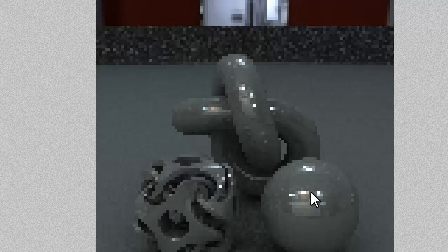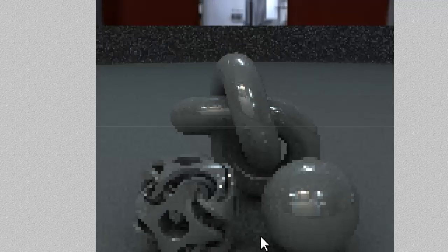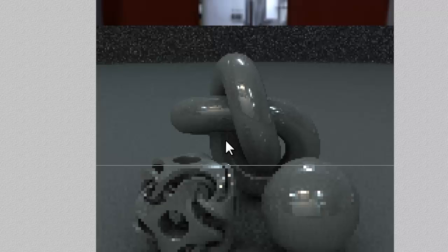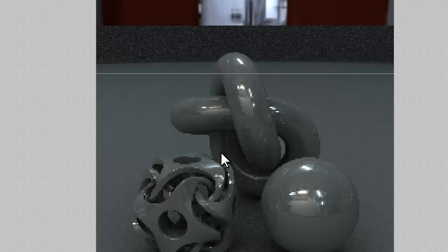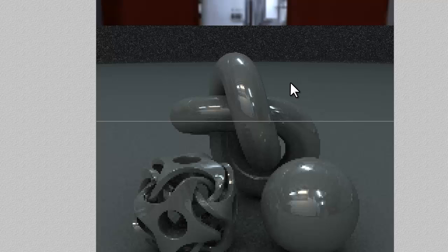Okay. So now if I render with this, I did it small so you can see the difference. We have got even lighting because it's a diffuse, and the simulated light sources generated at the world center spread out quite evenly on the diffuse inner surface of this light source, and then it's picked up by the true ambience effect and brought back in as a light source. So it looks quite similar to the specular convolved situation. It's coloured appropriately because the light that's been pushed out by the HDRI image is coloured.